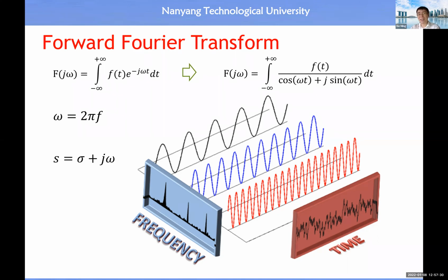It is the steady-state response in a system in which all the signals are sine functions. When all the signals inside a system are sine functions, then sigma equals 0, and then we talk about the Fourier transform. This is just for you to know.